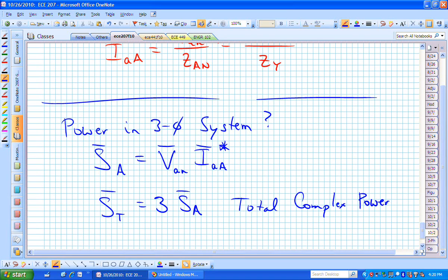Two ways of thinking of that, but the power factor is just cosine of theta, and we're assuming you find theta from that. And the reactive power, its units, VARs. What are the units on the real power? Watts. The units on the apparent power? VAs, volt amperes. See, you guys are getting ready for exam number 2, right?